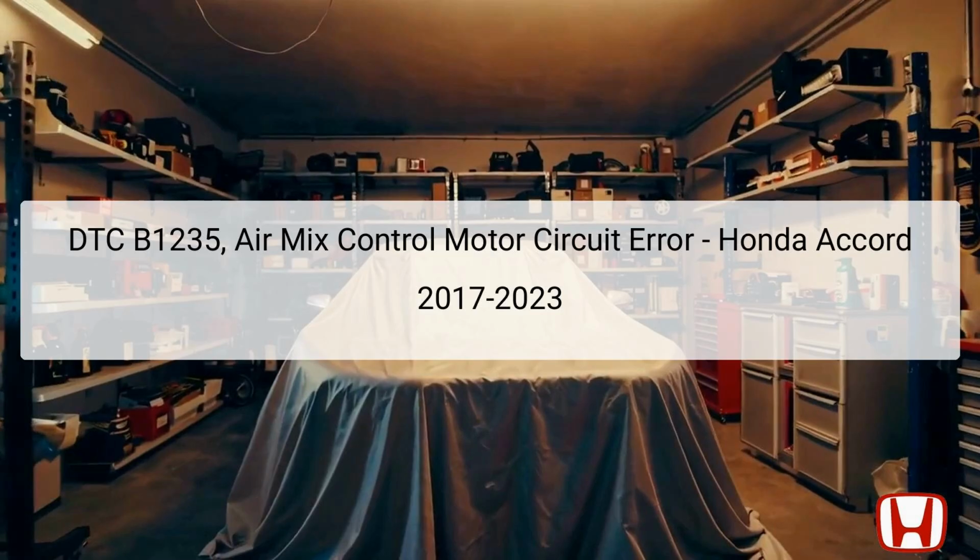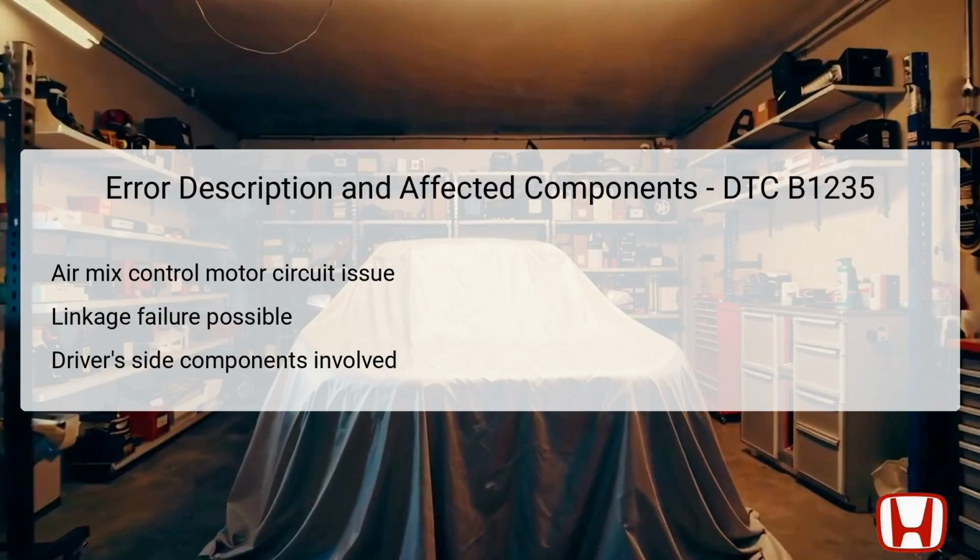The climate control unit manages various aspects of the vehicle's interior environment, including temperature, humidity, and air distribution. When a fault is detected, it triggers the B1235 code, prompting the need for thorough diagnostics to identify and resolve the underlying issue. DTC B1235 indicates a malfunction in the air mix control motor circuit, as well as potential problems with the linkage, the door mechanism, or the motor that operates these components on the driver's side of the vehicle.